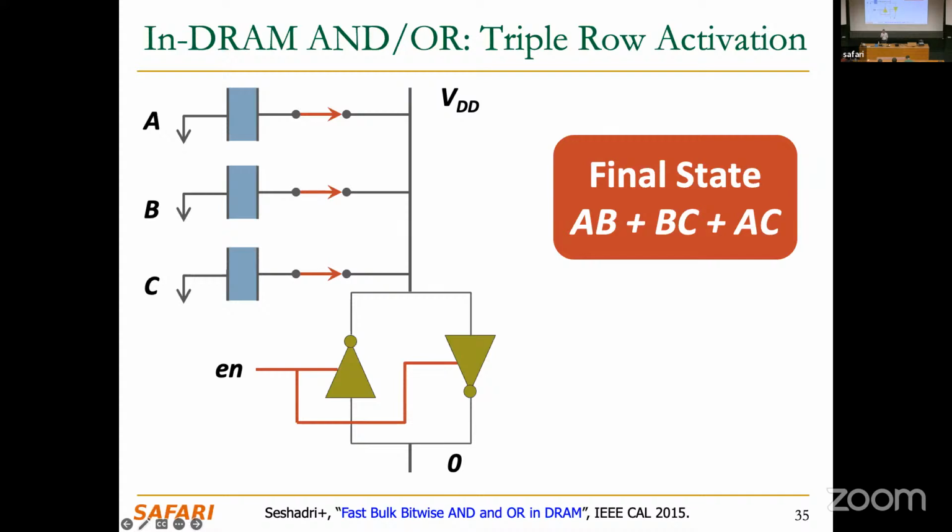because this sense amplifier here was not designed to drive 3 word lines at the same time, 3 cells at the same time. And as you mentioned, we also have to take into account the capacitance, or the impedance, of this line over here, which is really long.